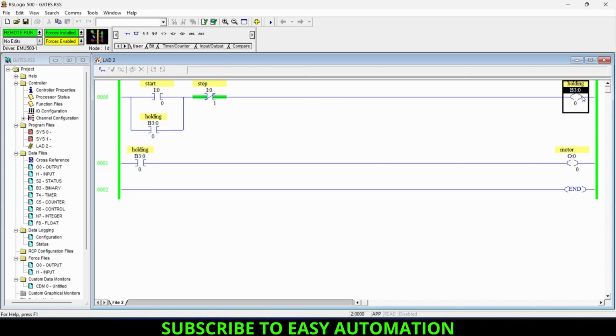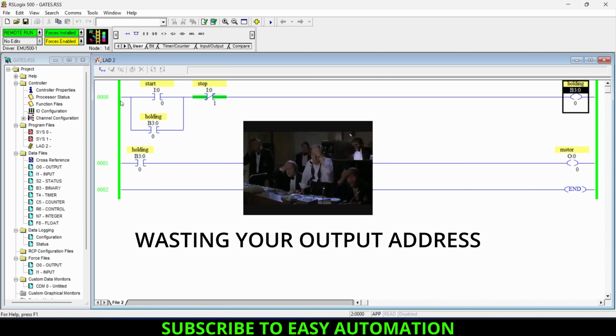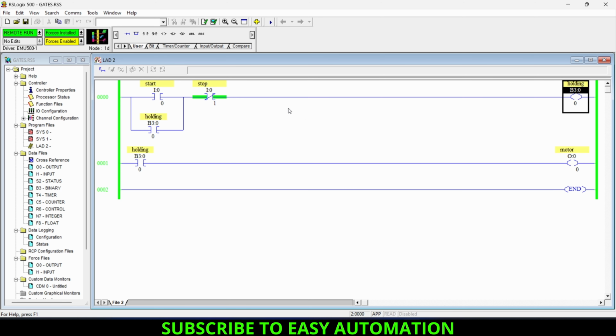So I have used one bit here for holding, which is the replacement of output coil and input instruction. And if you don't know about these memory bits, you will just use one output address here and you will just copy that address here as well. And that's how you will end up your program. But if you want to turn on this motor from any SCADA or HMI, you need to use the memory bits. So now let's talk about that concept.